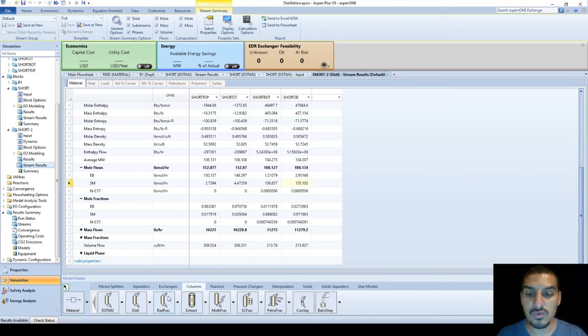So you have to go for the rigorous methods, which are the accurate tray-to-tray calculation methods. By doing this, you can get extremely reliable results out of the column. So again, these are estimates. They are good to give you values that you can give to the rigorous method column, so that you can get more accurate results more easily, without going through many trials with different numbers, without having any close estimate of what you need to use.